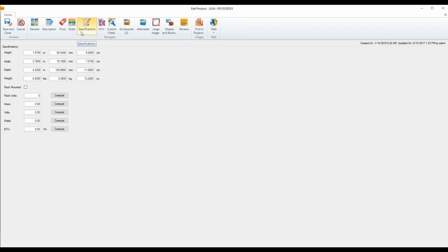We're also tracking some technical stuff too. Now, the reason we care about the specifications, the dimensions, is that this is used for the engineering side. So if you wanted to build a scaled rack layout, you can drag and drop the items out, make your connections, and it actually builds a scaled layout, making sure everything's going to work properly on the page. Also, power and heat ratings can also be used for devices where that's important. So you can get things like rack loaded ports if needed.